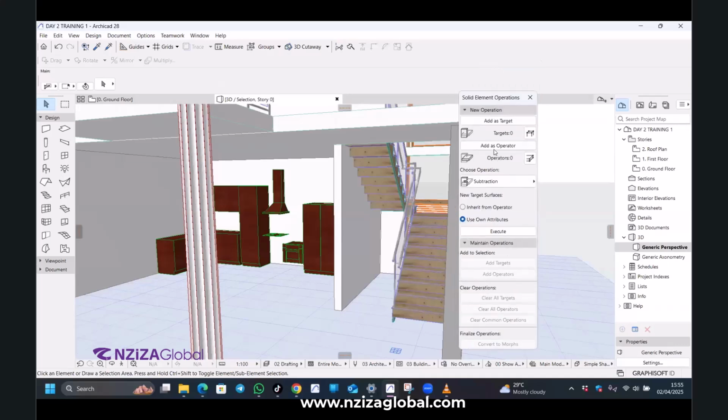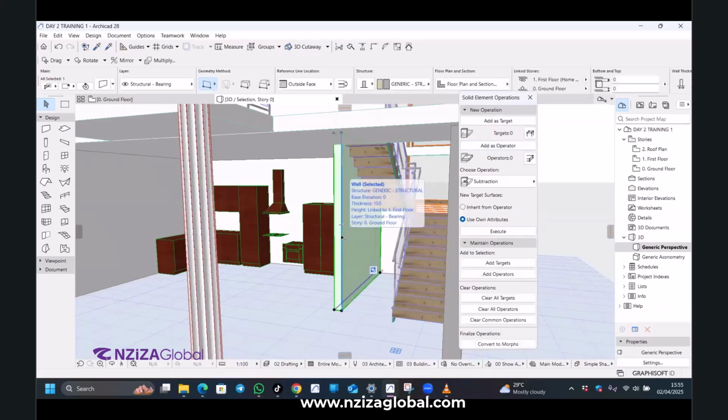There's a target and there's operator. Okay, listen. Target is what you need to cut. Operator is what you will refer to. So now you will select a wall, then click add as a target.